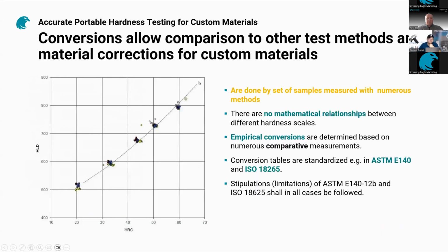So here on this slide, you see a little bit better that each of those points, which we've seen earlier, is an average of several measurements. And this is something I want to reiterate once more. One hardness measurement is better than zero, but it's not much better. Typically, 5 measurements would be something that a user should take into account. We're going to get there in a second.